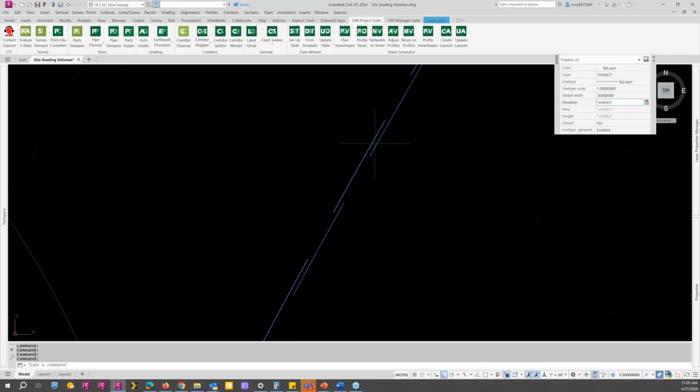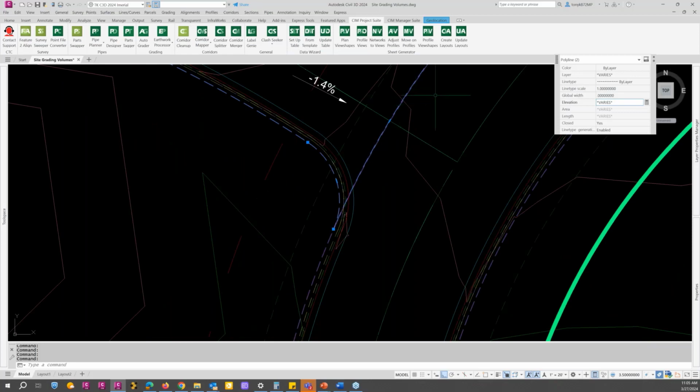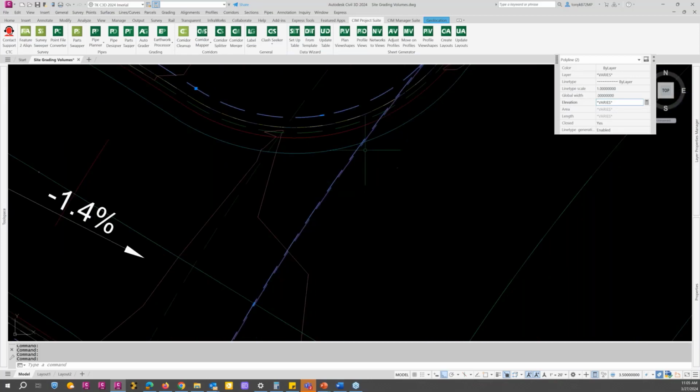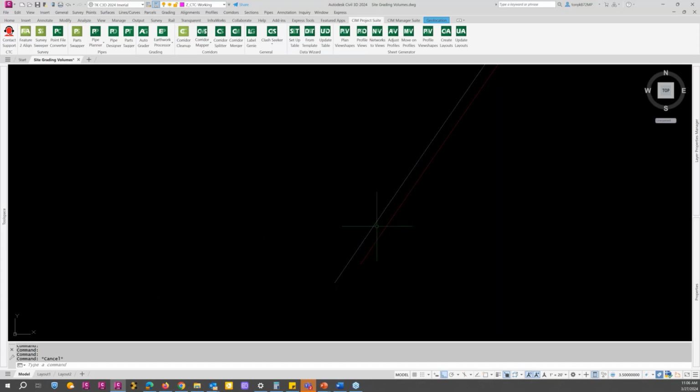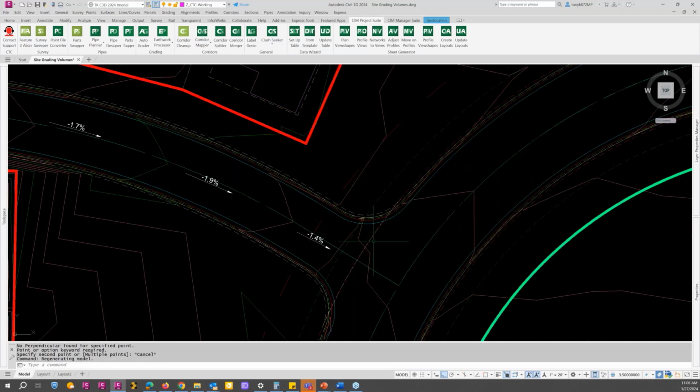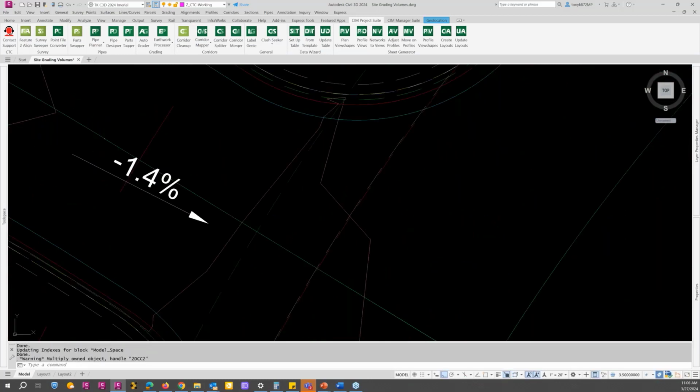Where these two connect on this road right here, where the main road gets subcut deeper than the adjacent roads, there are 2 separate regions for that depth, and they have to be apart. So these are 0.01 apart, and they could be anything you want, up to 8 decimal places, just so they don't touch. I use 0.1 just for display purposes.